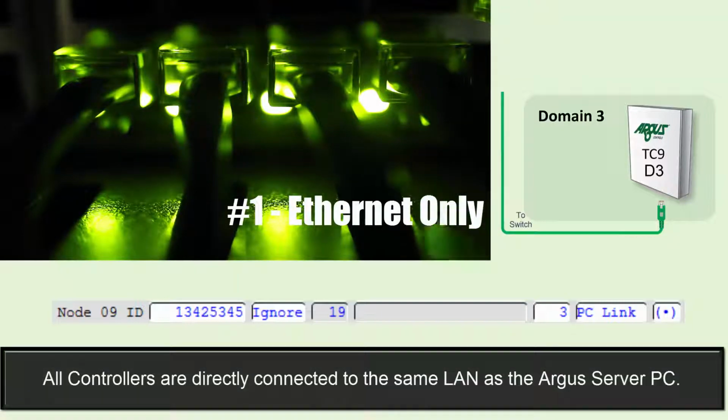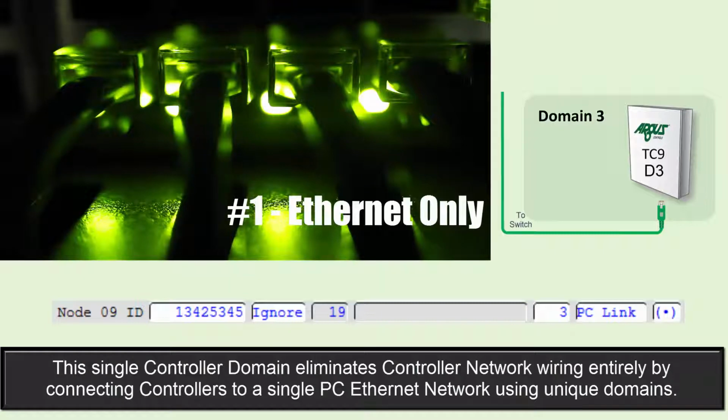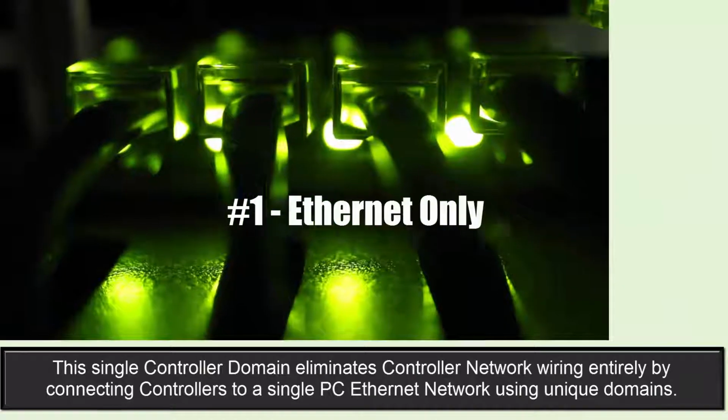All controllers are directly connected to the same LAN as the Argos server PC. This type of single controller domain eliminates the controller network wiring entirely by connecting controllers to a single PC Ethernet network. Each controller is assigned to a unique domain.